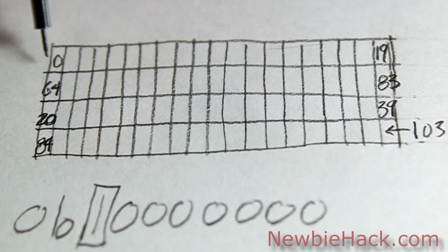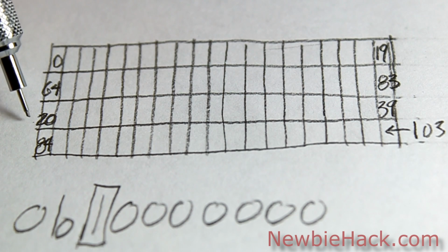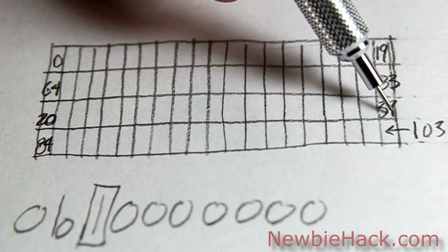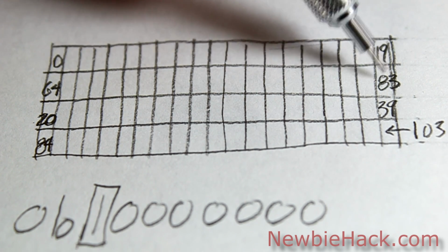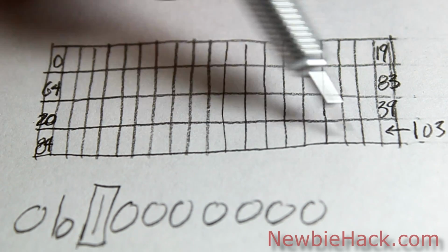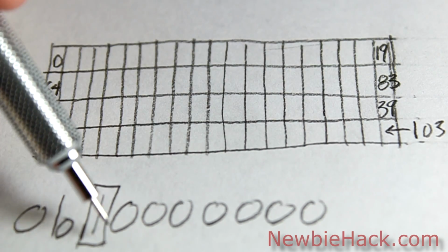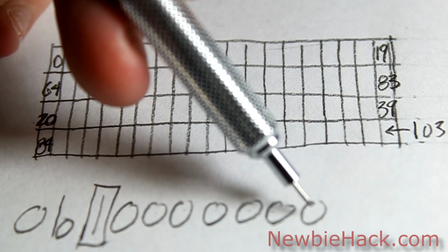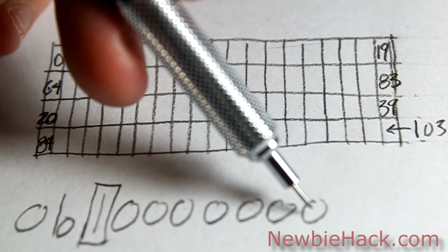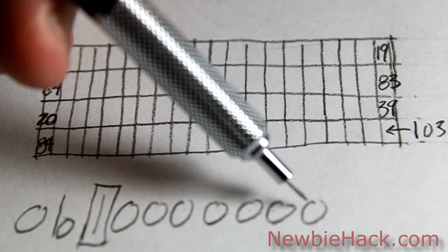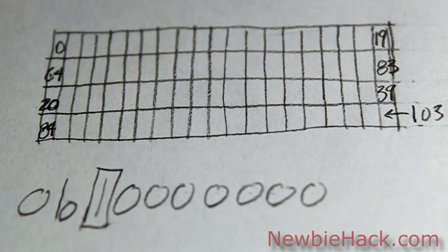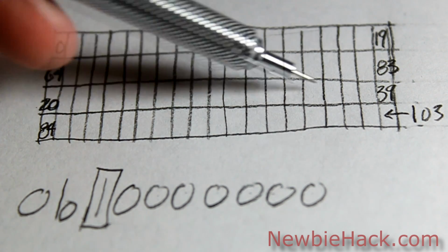Now you'll notice that going from 0 to 19, it jumps to the third line, 20 to 39. But then from 39, it jumps all the way to 64 for the second line, and then 83, and then it goes on to 84 to the next line, to 103. Now, you'll notice that if you convert 7 digits of a binary number, the maximum number you can have is 128 different numbers. So any LCD that is using the particular integrated circuit that this is using, which is actually pretty standard, you probably never have more than 128 locations on a particular display.